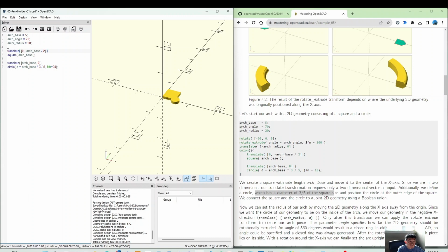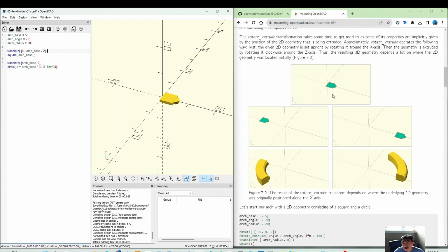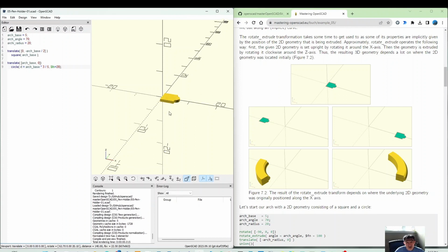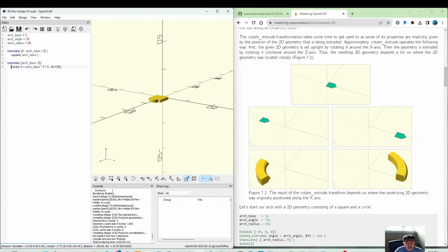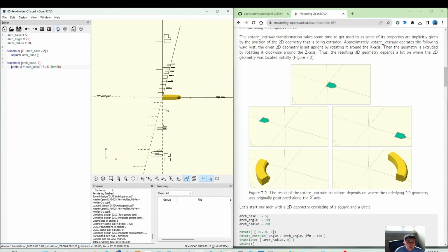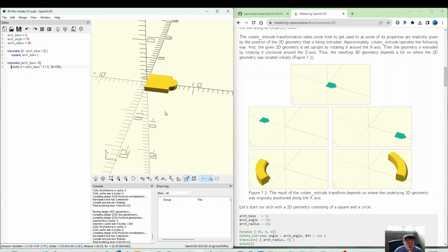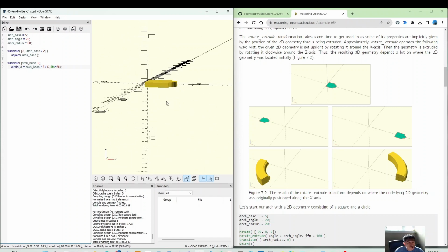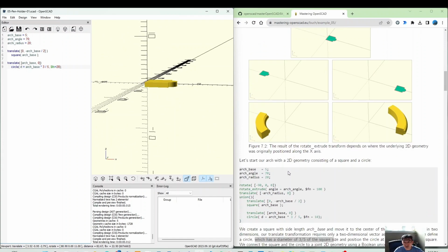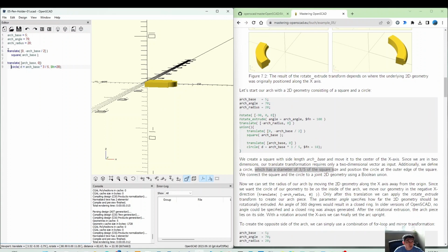Then we have this one. So first we have this shape. But remember, we mentioned in the last video, even though you see this as 3D, when you press F6, you can see this is actually just our 2D shape. It doesn't mean it has thickness. The thickness is just during the preview with F5, which shows you something in the Z area. So that should be remembered clearly, and don't confuse 2D and 3D.